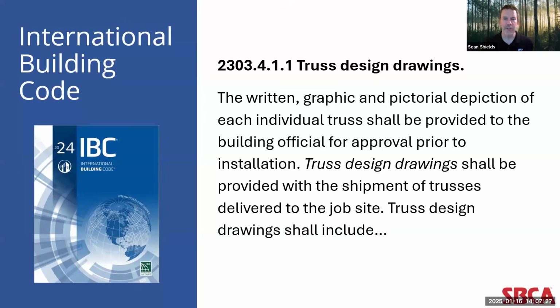Now, as we begin our discussion on truss design drawings, I do want to start with the codes and standards references that provide the basis for what is included in these important documents. A truss design drawing, or again, a TDD, is a document that provides a graphical representation of a singular truss and includes very specific information for structural engineers, building designers, and building officials to review.